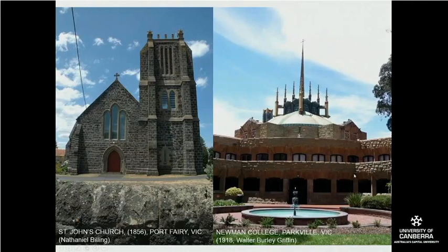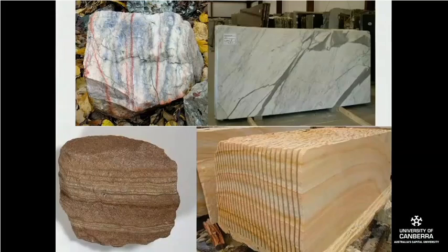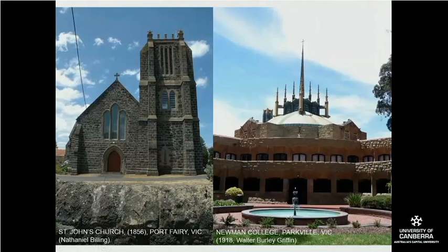because if we go back to this slide here, the way you're supposed to lay sandstone is like this, with the layers going horizontally. But for some reason, at Newman College the layers were actually laid vertically, which meant that the water was able to start to degrade the different layers, which has led to a very expensive and long restoration process. The problem has been overcome with modern, very expensive sealants which don't look like they're there.